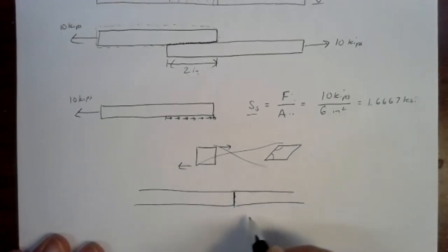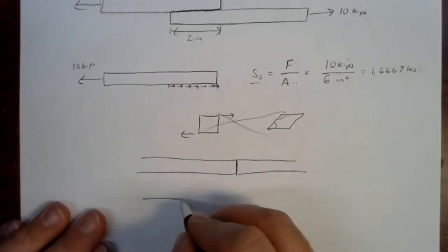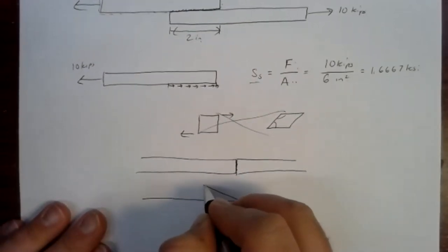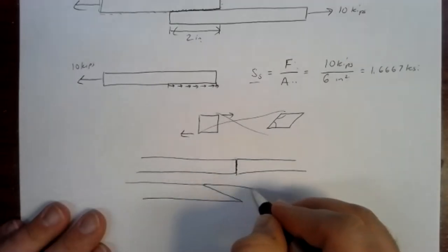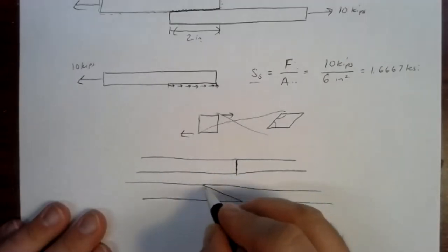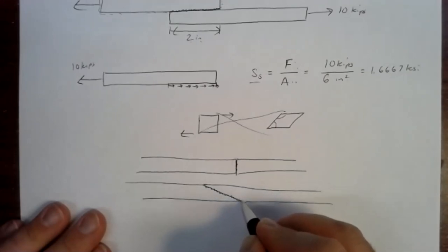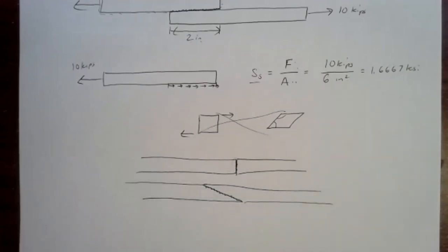material. On the other hand, if you do what we call a scarfed joint, where you cut the material back at an angle, something like that, what you're really doing is just expanding the area that glue has to be on. So you lower the overall stress.